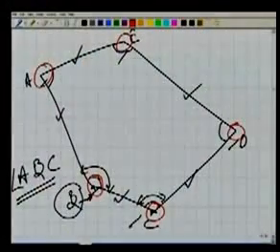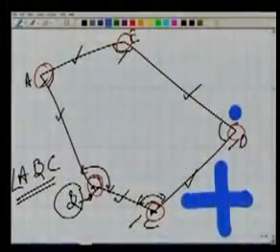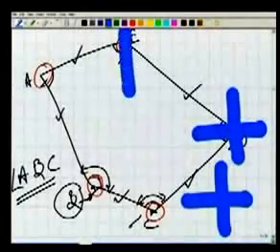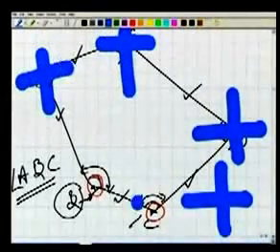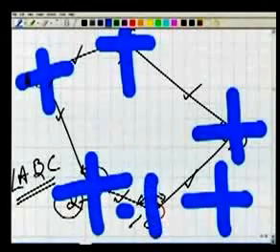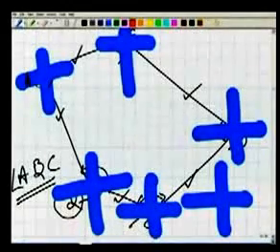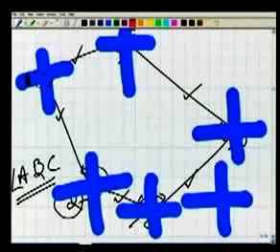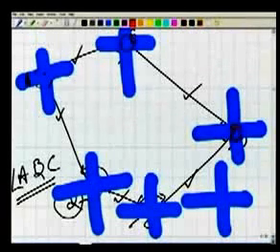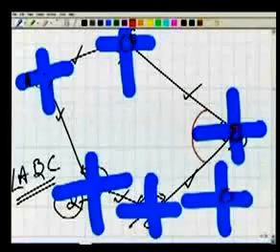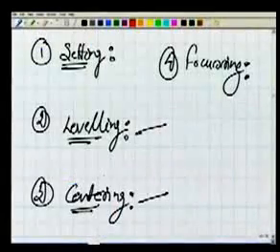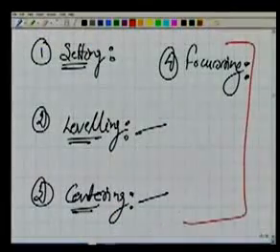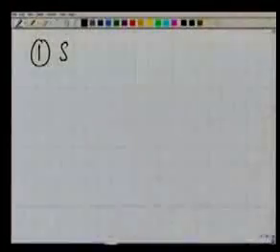Or if you are doing temporary work, you can take some paint and draw some lines on the ground to mark the stations. These are the lines which mark the point. The job is, when you are occupying a station, you want to put your instrument over these points. This is how you can measure these angles, and this is why we need to do all these temporary adjustments. Now in these temporary adjustments, we will start with one about the tripod.